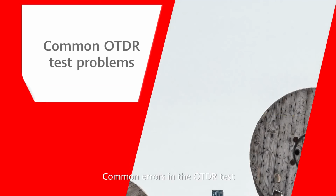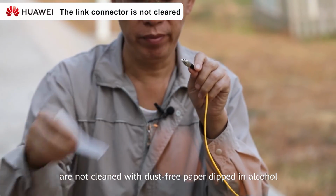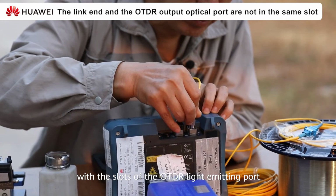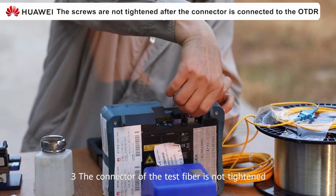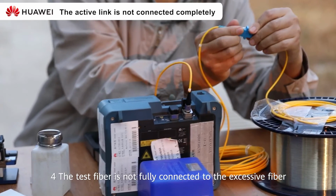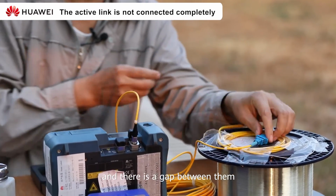Common errors in the OTDR test. 1. The test fiber ends connected to the OTDR are not cleaned with dust-free paper dipped in alcohol. 2. The teeth of the test fiber connector are not aligned with the slots of the OTDR light-emitting port. 3. The connector of the test fiber is not tightened after being installed on the OTDR light-emitting port. 4. The test fiber is not fully connected to the accessory fiber and there is a gap between them.